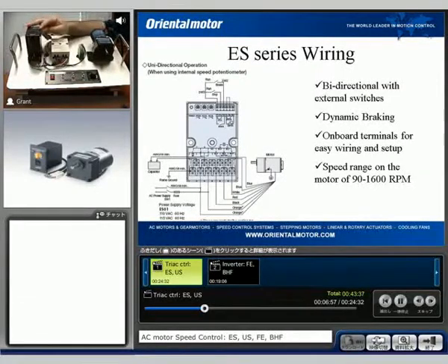This box over here is actually a speed output display, and unfortunately you're probably not going to get a very good look at it. But essentially what this does is it takes the tachogenerator feedback reference and outputs a digital display in RPM. Now this is our V Series induction motor, which is the higher gear life rated and quieter operation type gear system, and much higher output torque. And of course we have the capacitor, since all of our motors do run off of a capacitor.